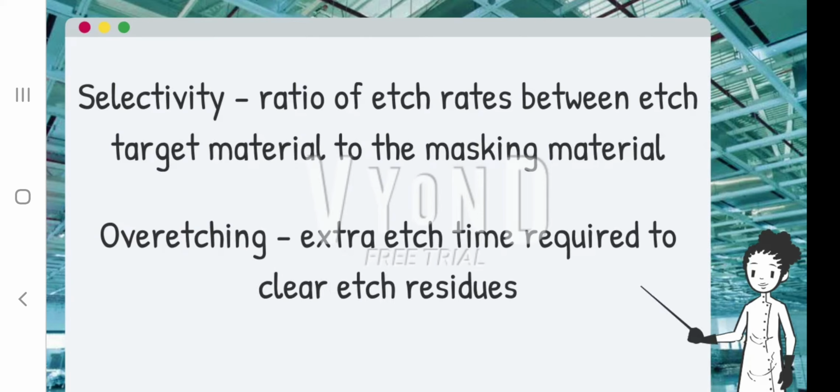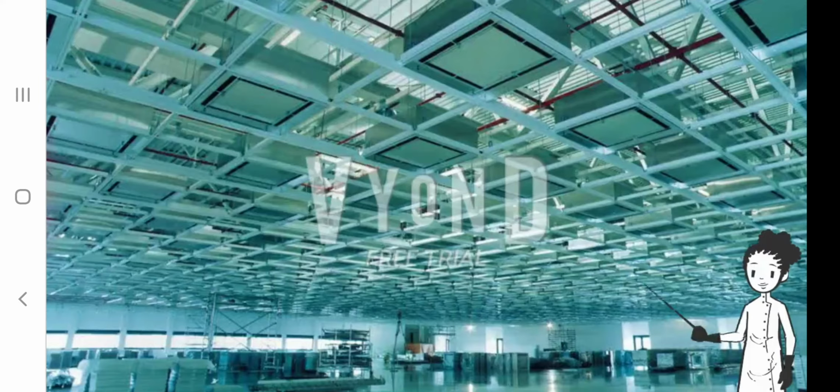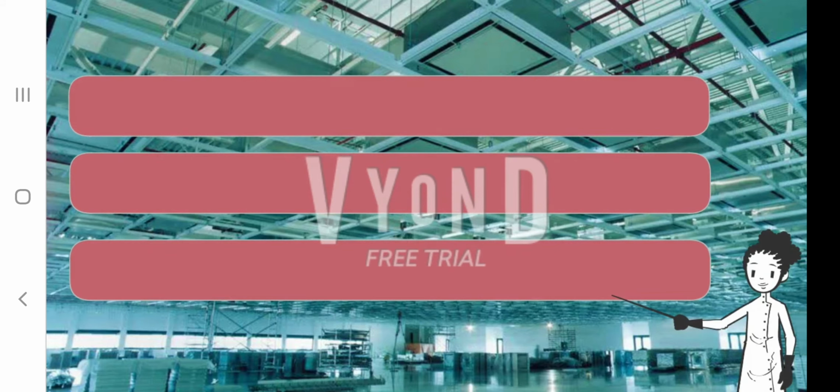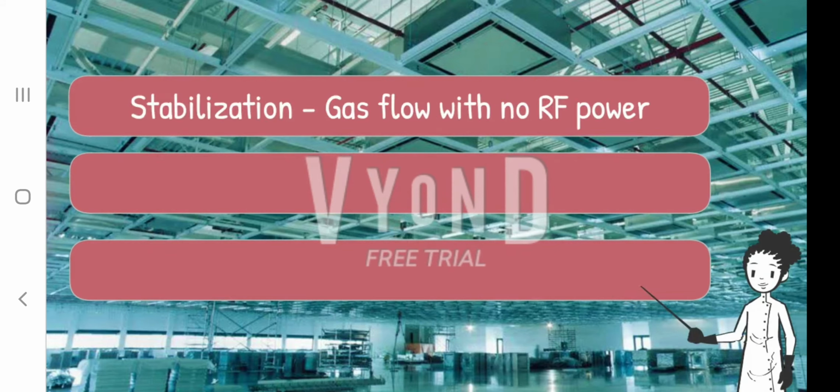Extra etch time is required to clear etch residues at the endpoint due to etch rate non-uniformity and the underlying layer topography. Etch process has three main steps. First is the stabilization step. In this step, there is only gas flow with no RF power. This step is to stabilize the gas flow and the pressure setting.